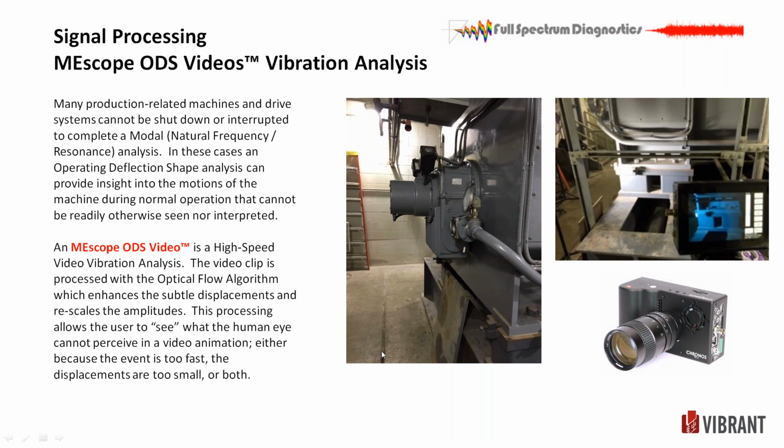You can see the floor here, this little gasket. The slab is separate from the building foundation, and that slab was vibrating. So we turned the generator on at 1800 RPM. It was putting vibration through the whole structure, and the whole slab was vibrating at about 3 times the level it should have been. A lot of vertical vibration. So we're going to look at this in a little more detail, and we're going to walk through some different parameters that you might not have thought about, and a couple that we just put together this week.